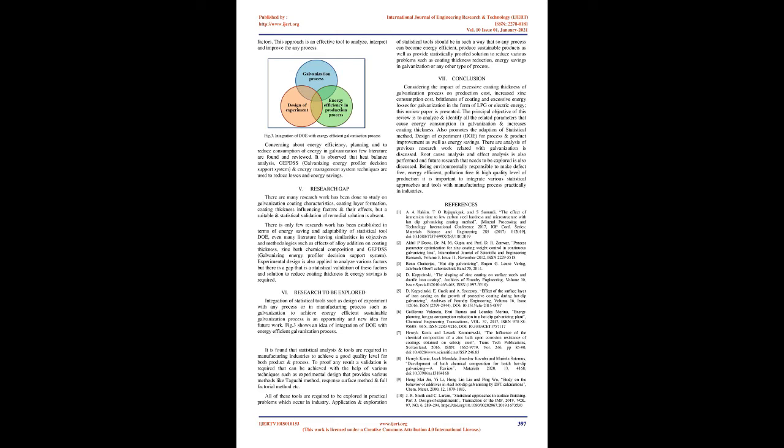Material. The coating thickness varies due to reactivity of the steel or iron work material, presence of silicon, and also the size of the work material. Method. Another problem arises from the method of the galvanization process. Lack of planning about dipping weight standard, especially in case of dipping into the zinc pot where the number of work materials is to be standardized according to size, dimension and weight.